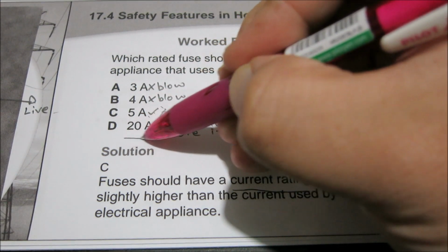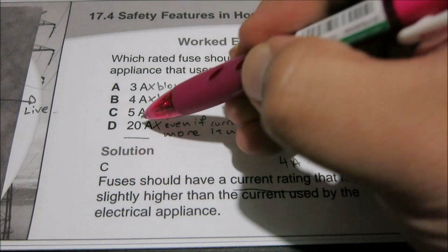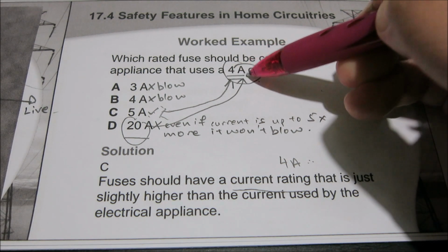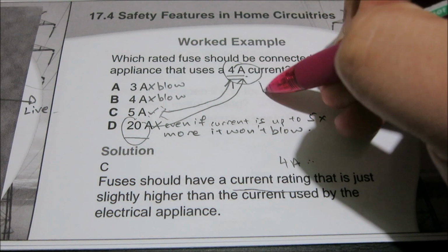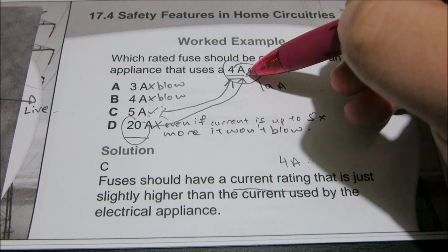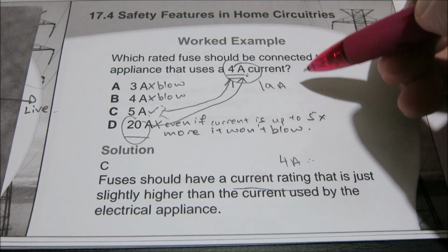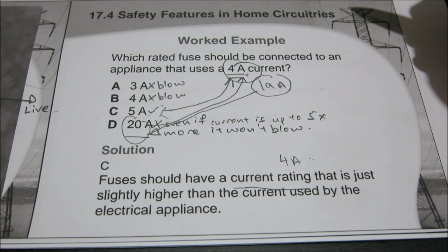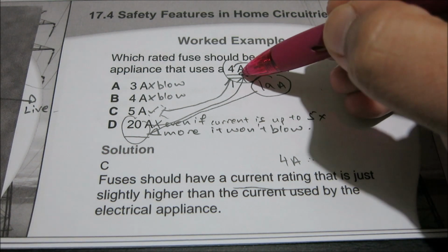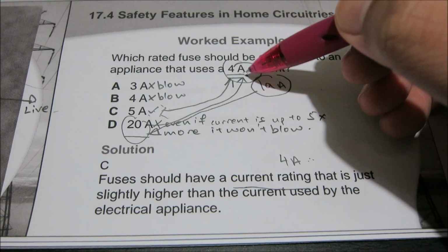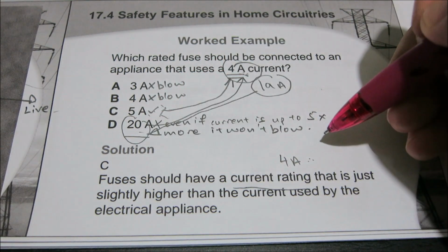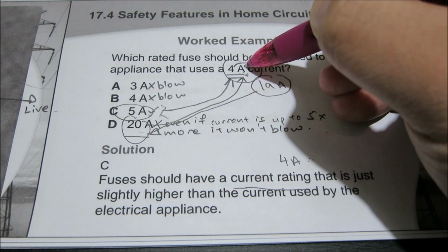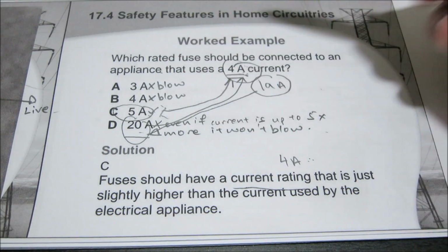Now, it is not desirable to use a fuse rating that is way too high compared to your normal operation current. Why? Let's say my current can go up to 19 amperes. Remember, your appliance is rated for only 4 amperes. Even if my current goes up to 19 amperes, my fuse will not blow. So this is not a useful safety device now. Likely your appliance will fry, heat up, and cause a fire before the fuse will blow. So in general, when you're looking for a fuse, find something that is just slightly higher than the normal current that is drawn when you're using the appliance normally.